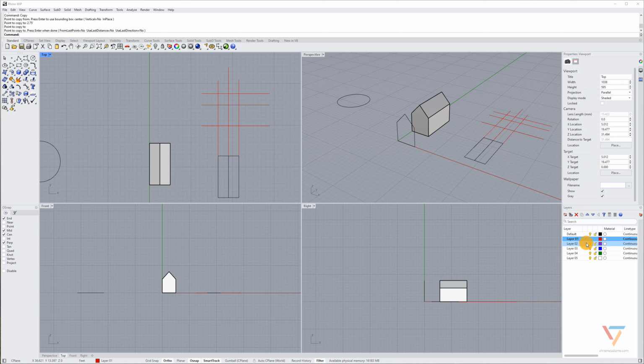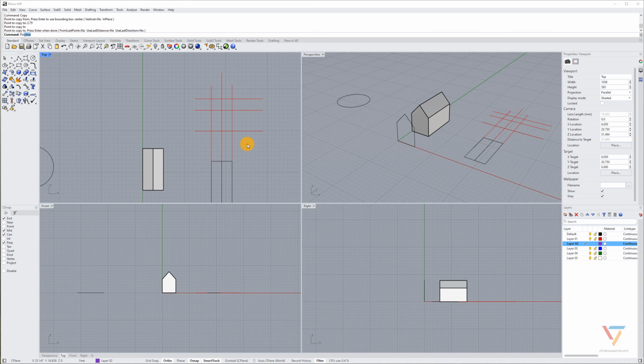So let's go back here to, let's say, layer 2. I'm going to say polyline, and now I can use these vertices here, and let's make sure that I use intersection, INT. So that would snap here, here, here. This is that midpoint of the roof, down here and down there. Now I'll turn off layer 1 by clicking the light bulb, and that'll hide it.